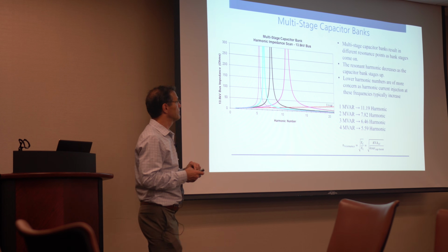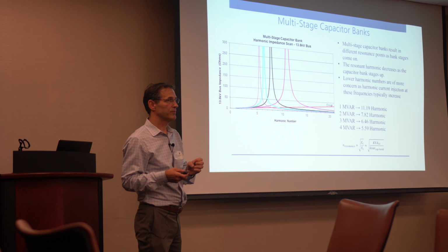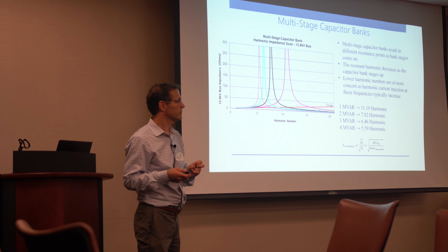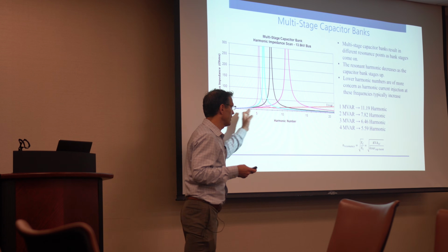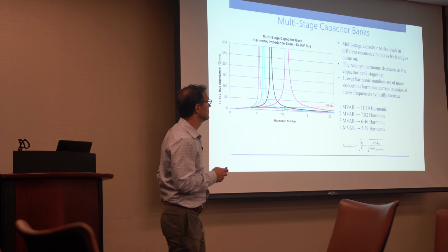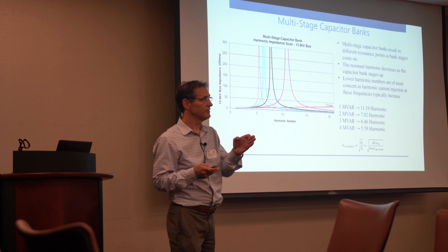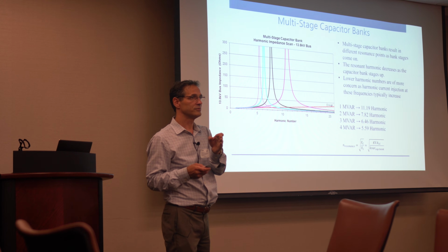So you get a shift in resonance, which means that if you're installing power factor correction and it's automatic banks, you've increased your odds of having a problem, really, is what you've done. And you have resonance concerns at each one of those locations. Your study must account for each operating condition.